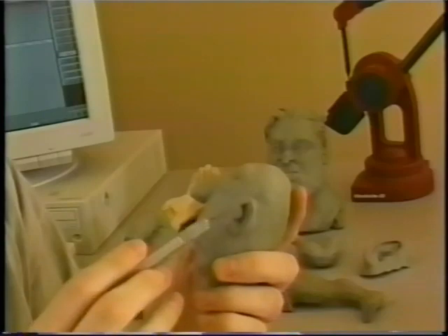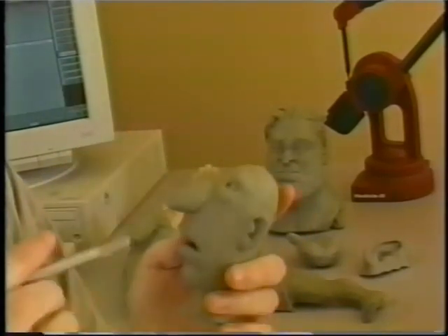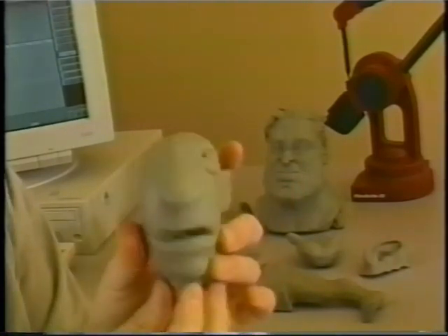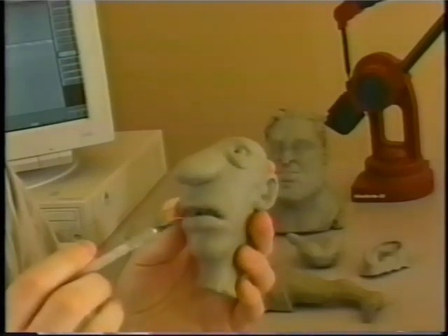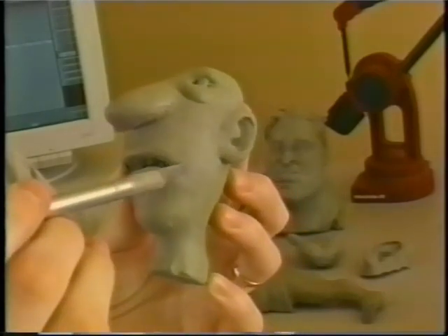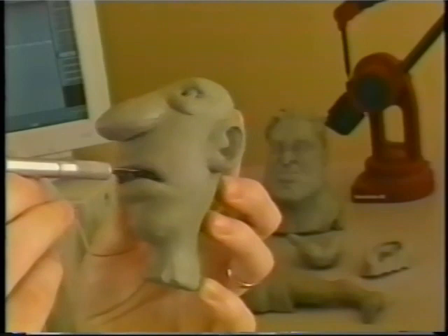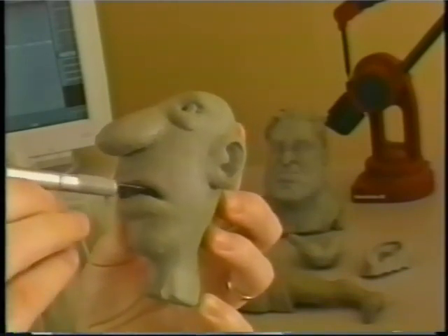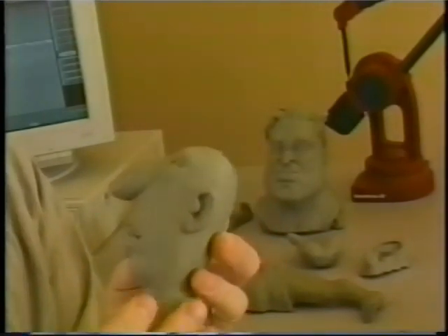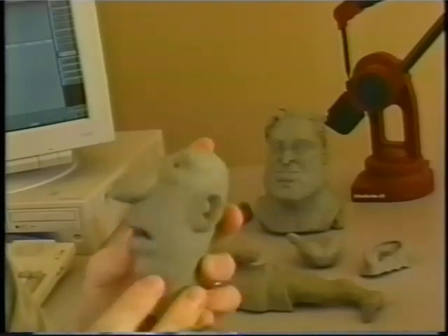So this whole surface, except for the ear, which is attached on later, is continuous from top to bottom. And if you need to add more detail, you just add more lines one way or the other. And when you get to the inside of the mouth, you need to have many more points along here to go inside. What you can do is put a transparency map in there so it actually disappears, so it looks like the mouth is deeper than it is. So you don't have to use too many points in there. So that's one way that I like to do heads.